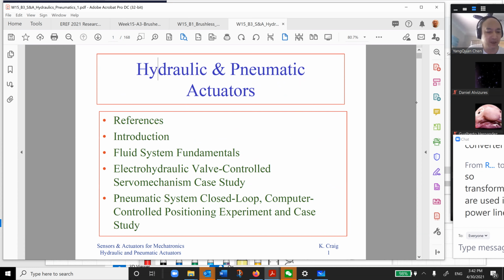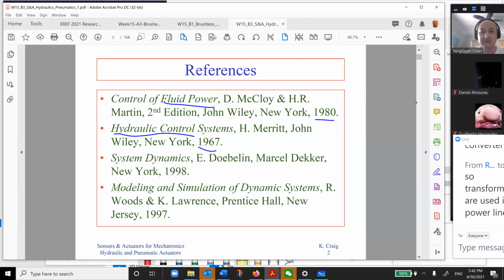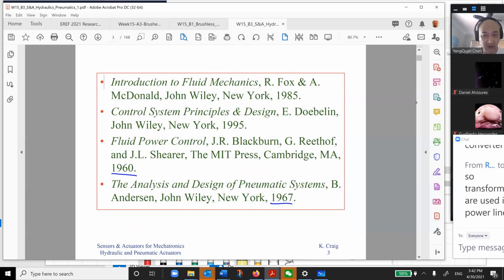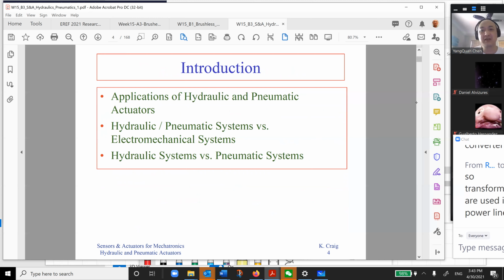Say, for example, you have seen the garbage collection vehicle. You have an arm that lifts your garbage bin. Those mechanisms are pneumatic or hydraulic. It's hard to believe you could use a motor. You cannot provide that level of torque at all, or your motor would have to be very big. Make sense? So that's the key difference between hydraulic systems versus electromagnetic systems based on motors, okay?